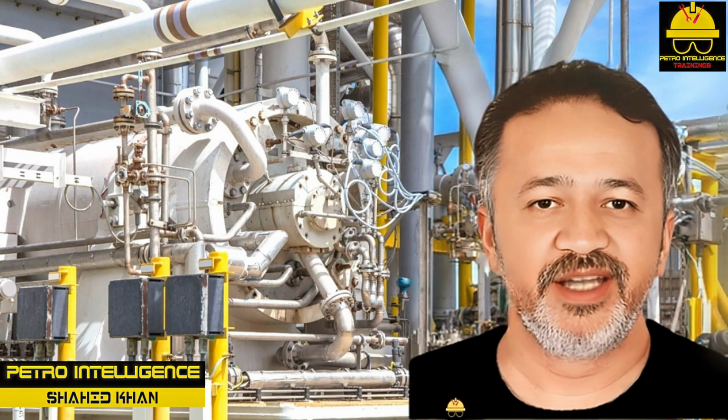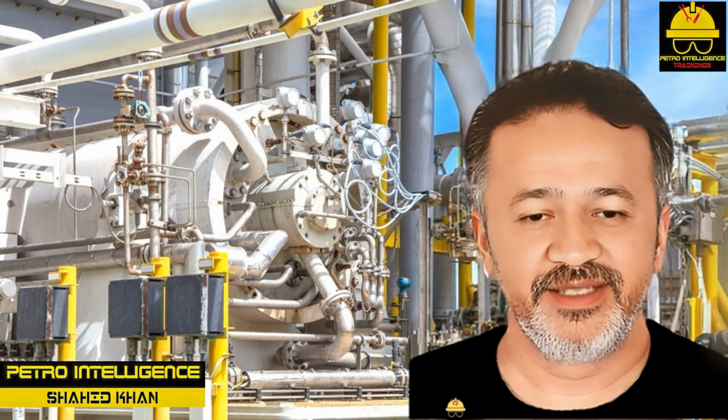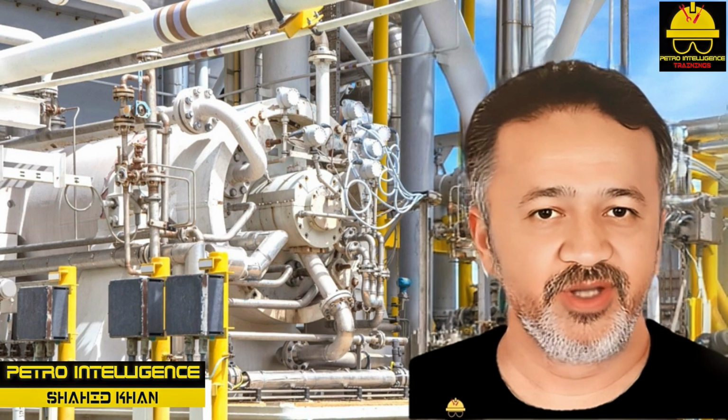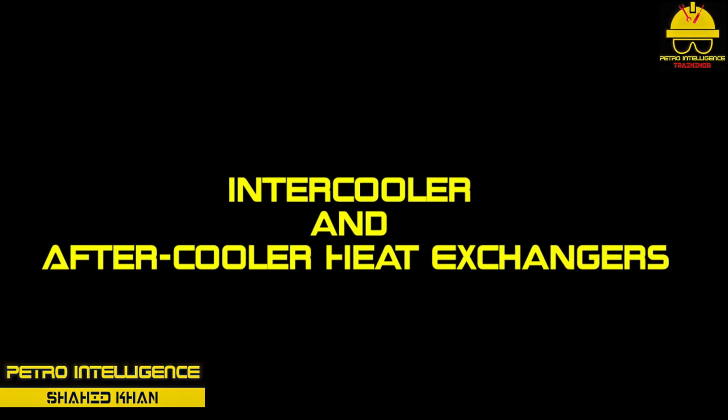Supporting equipment in a compressor system. When compressors are used in a process system, a wide assortment of supporting equipment is required as shown in picture. Some of this equipment, such as filters, drivers, and seals, will be described in other training. Here we will describe intercooler and aftercooler heat exchangers, safety valves, silencers, demisters, and dryers.